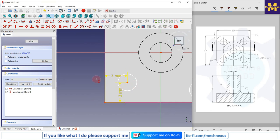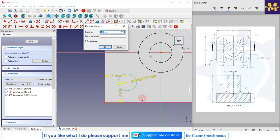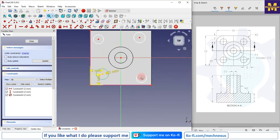Now I will select the circle and give the diameter 2, and now we will constrain the other circles. Select these center points and these center points and give the horizontal constraint, then select this center point and this one and give the vertical constraint, so we can see that the vertical position is 2 mm.